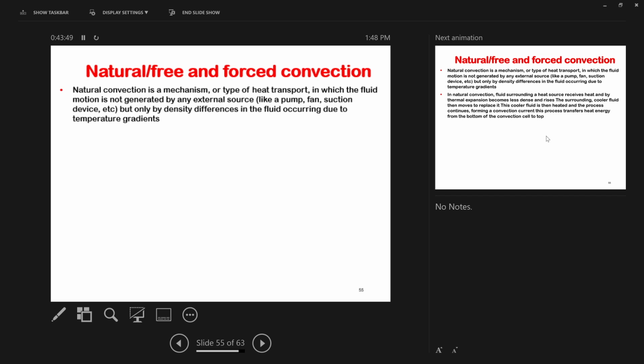Does that make sense? So it's the concept of diffusivity you mentioned earlier, right? Yes. It is a combination of the two, advection, because you can have both movement of air as well. Right. Okay. But the main part that you need to keep in mind is that you are going to deal with the buoyant forces a lot, right? Buoyant forces become very important because you will see the density difference. Does that make sense? Okay.